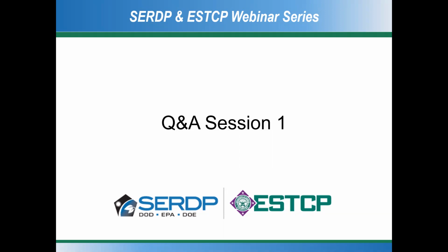Great, thank you. Here's another question from the New Jersey Department of Environmental Protection. Have you considered iron as a potential problem with the biofilm and the catalyst? Okay, that's a pretty good question. So what could be a problem with iron? If you had a high iron concentration, it probably would be ferrous iron. I don't think that would have any impact in the first stage. The second stage, it might create a problem if you started oxidizing the iron and precipitating iron oxides in the biofilm, and it could cause some operating challenges.